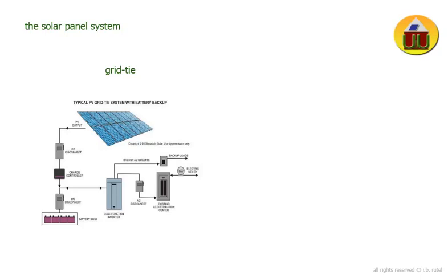For this type of system, you still have an electrical bill, and you will use the power from the solar system when it is producing, and you will use grid electricity if you have a cloudy day or a broken system. If you are not using all of your power, then the electricity you are producing can also go back into the grid, since you are connected to a commercial provider and essentially producing power that can be used elsewhere within their system. For this reason, there are certain requirements in the quality of the electricity you are producing, which you need to meet before the utility company will allow you to send power out. This is taken care of in a component called the inverter.